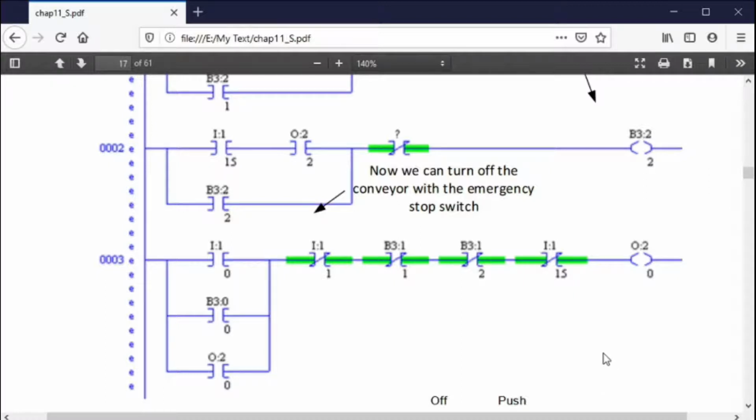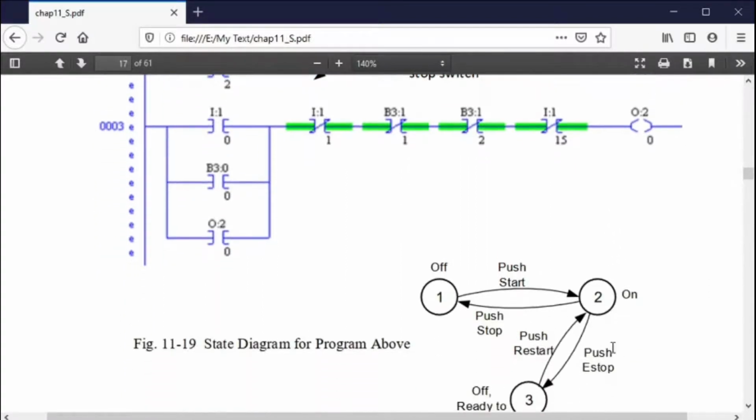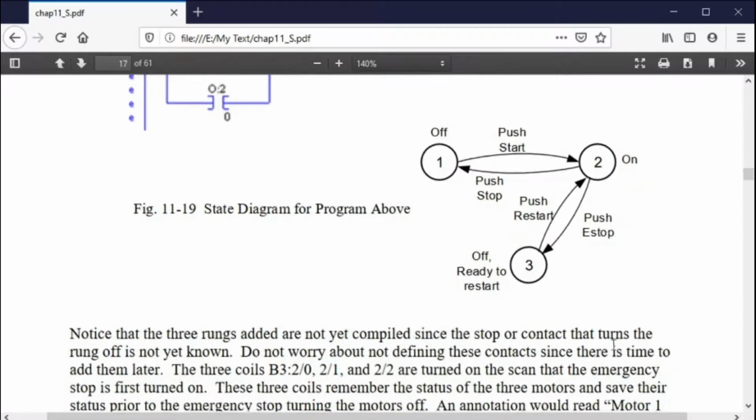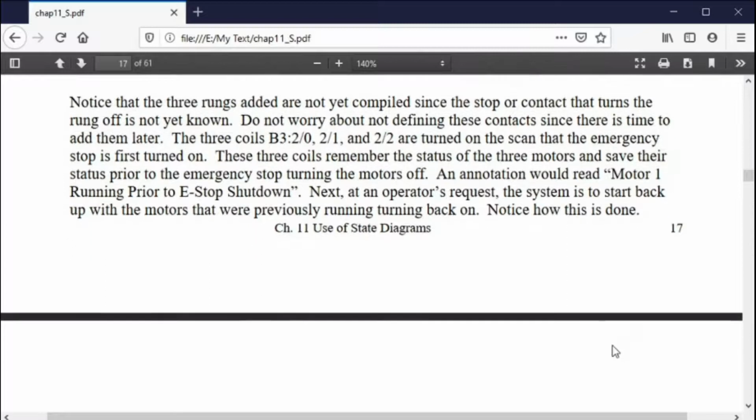You say, would this ever work with relays? No, it never would, but this is something where you use the cyclical nature of the scan to actually be able to set various states in your program. And that's all I'm trying to say. You say, well, it's a trick. No, it's the use of scan to make your states.